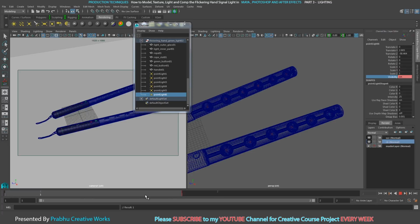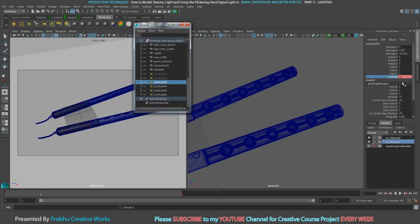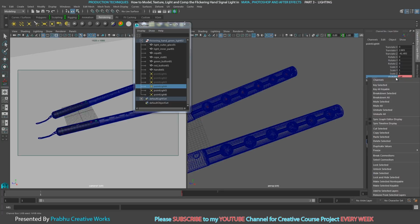So then go to the first frame, select the first frame, and then select the point light to off. In the first frame the green light should be off. 0, enter. Right click and choose key selected. So you want to give all the other lights off in the first frame. Right click, key selected. So select this one, 0, and press enter. So right click and choose key selected. So select this one, 0, enter. Right click and choose key selected.